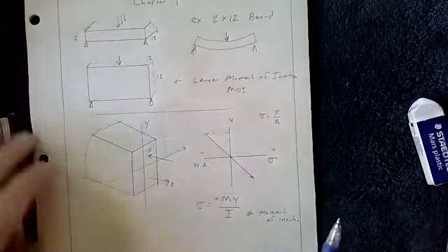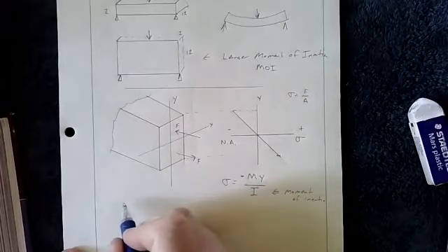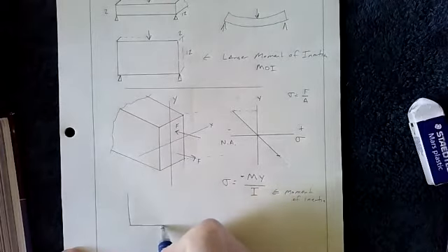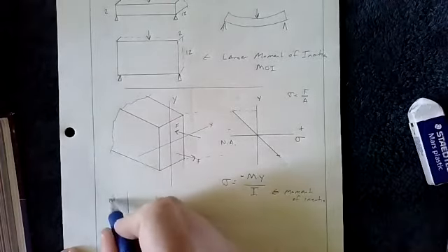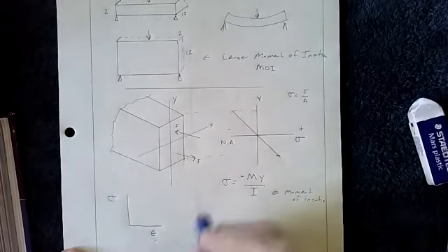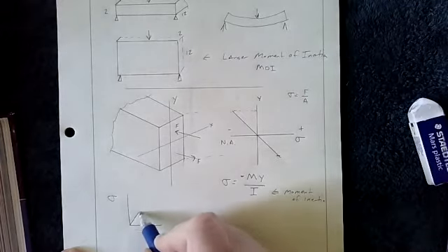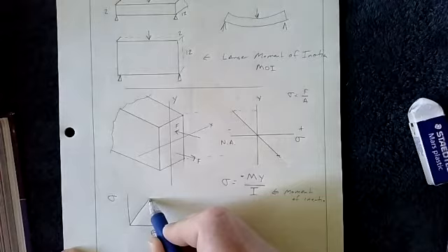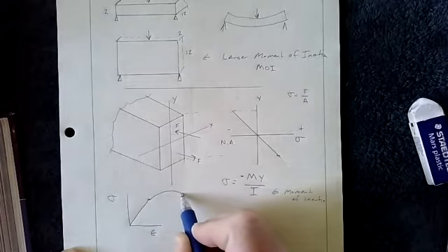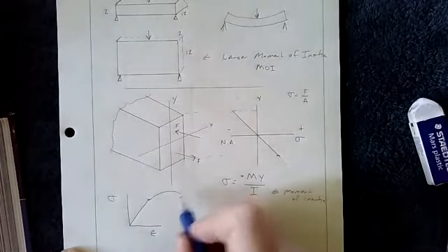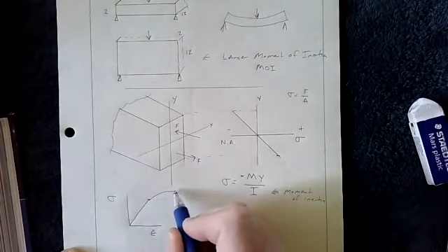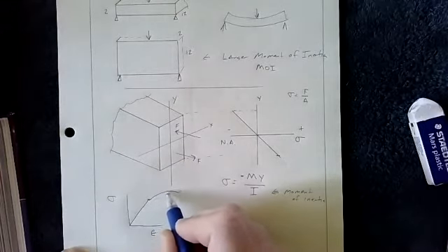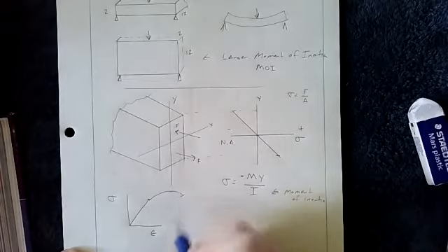If you think about material and you have a typical tensile test, stress versus strain, you know that it goes something like this, and then it reaches a point which is called the yield point. There's a little transition, and depending on the crystal structure, it'll keep going. They all pretty much look the same. They reach a peak stress, which is your ultimate tensile stress, and then there's fracture.